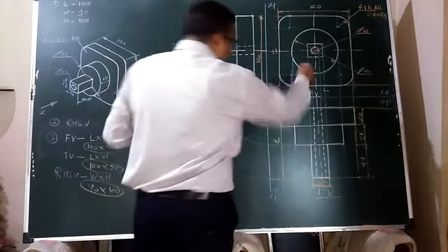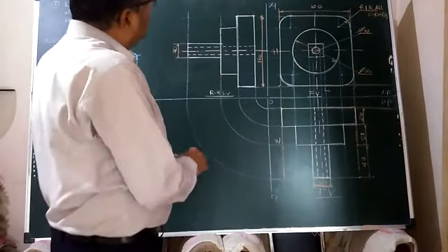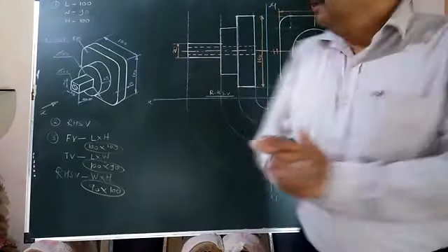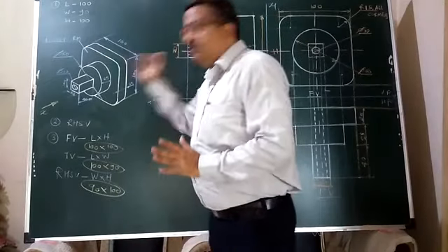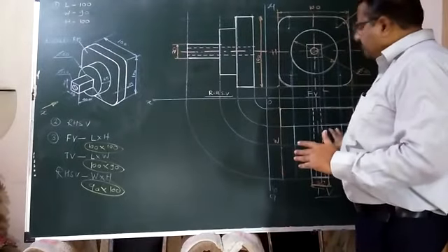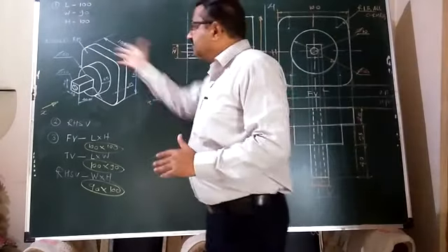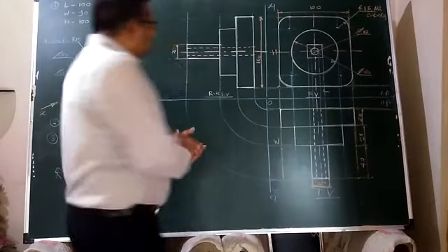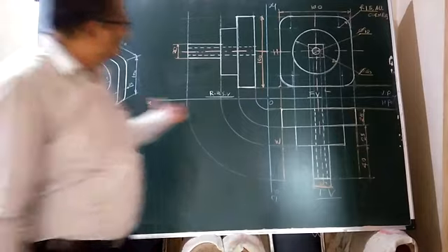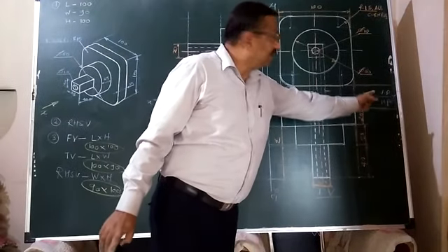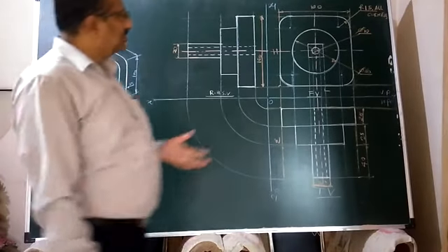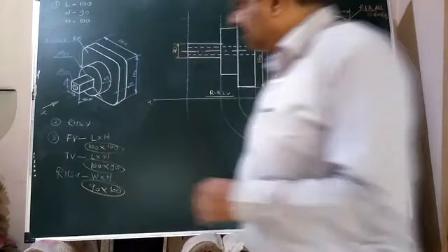So front view image, top view image, and right hand side view image. This is the solution which was expected from the narration. Figure shows pictorial view of an object in the direction of x. Draw its front view image, its top view image, and respective right hand side view image. All the three figures we have finished here successfully. Okay, naming is also completed. Vertical plane, horizontal plane, one should write here. Don't forget to write there. It indicates by which method of construction you have finished this exercise.